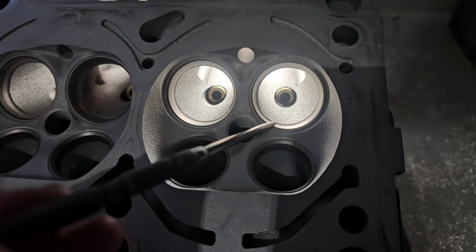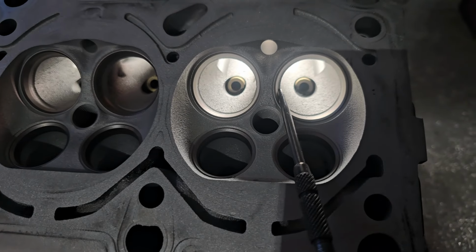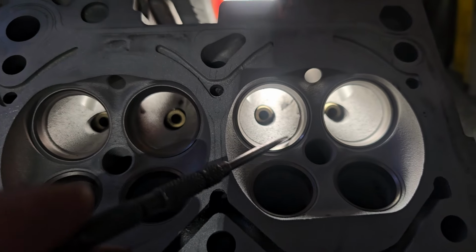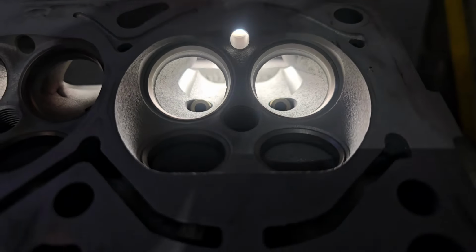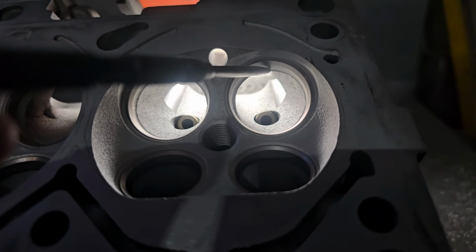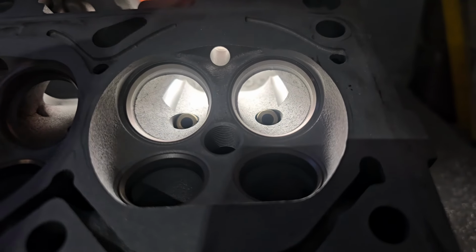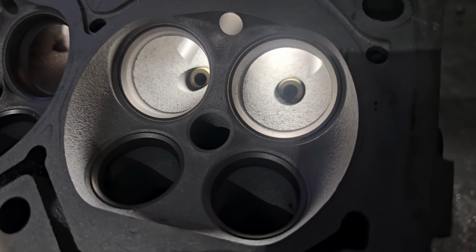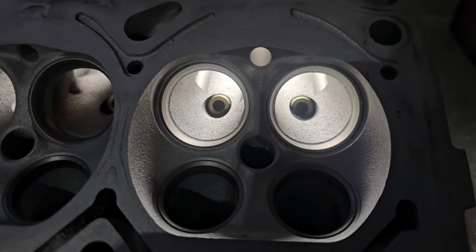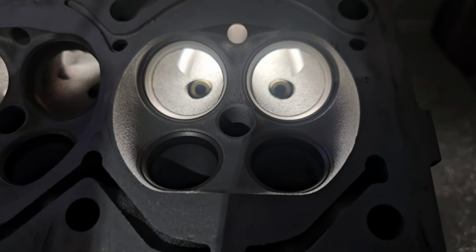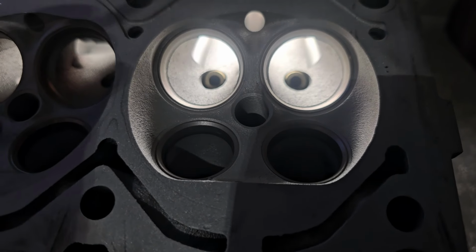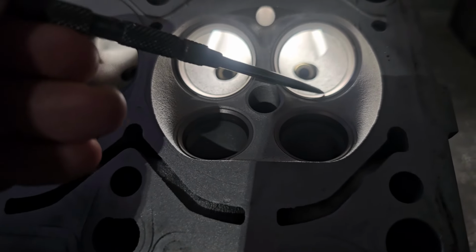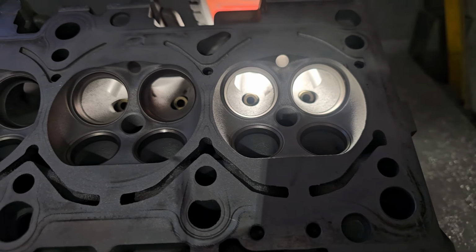So guys, you can see straight away it's got a bit of core shift. There's almost nothing there. And then we have about a 40,000, 1 millimeter, 40,000 step there. So we have a little bit of core shift in these ports. And we have a really, really big lip on the short side. We're just going to lay that to the seat and go through and clean this up. Yeah, quite a big transition from the seat ring, as you can see, to the casting. So we need to make this casting bigger to transition that 1280 to the 1400 or so square millimeters.